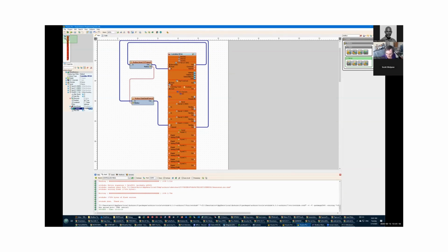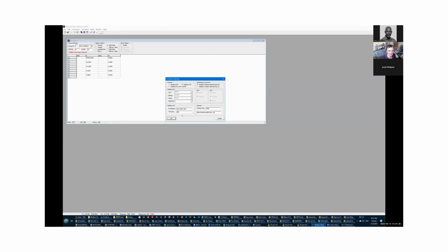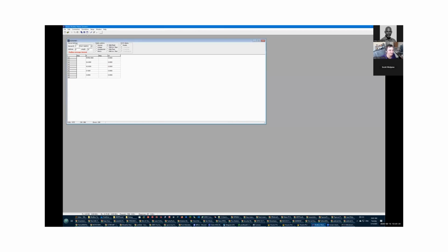And now we can see whether or not we will read some data. In this case, in the settings, we'll connect to 201 device, which is the new device. And voila. Do you see what we did? In 40 minutes, while talking and stuff like that, I programmed one device to work as a controller, collect data, send it over Modbus. And then I programmed a separate device to bridge from serial Modbus into TCP/IP and send it to my computer. And we did that in 40 minutes while just talking.